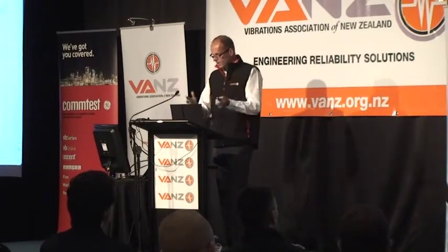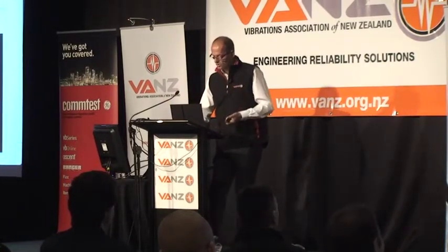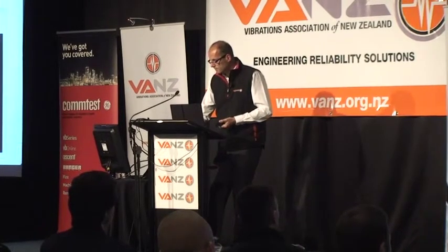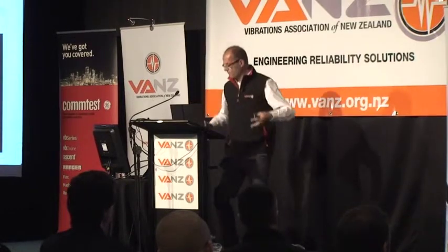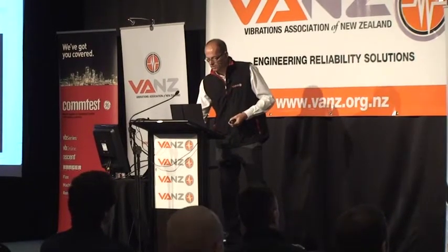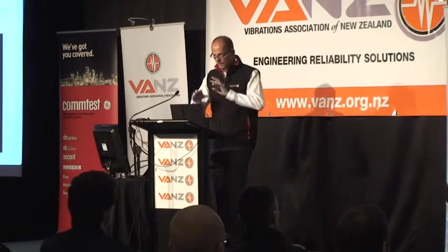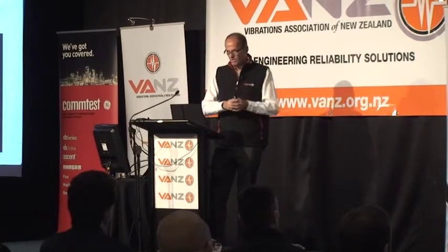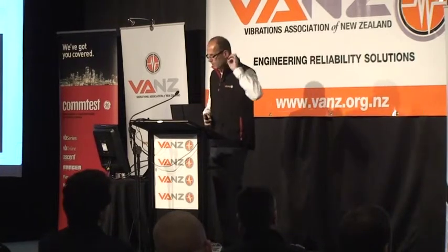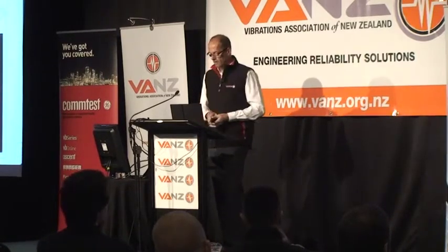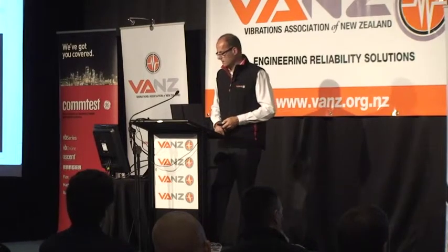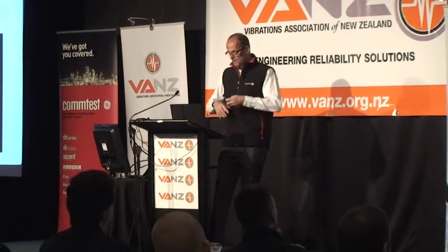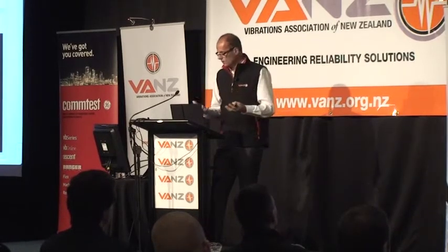So the machine makes all these sounds, and all we've got to do is use our vibration analyzer to say, let's listen to it here, because we can sense the vertical vibration, and we can listen to it over here, and as long as we're collecting the right information, then we can tell. We separate all those sounds into what's happening with the rotor bars, the bearings, and everything else. And like I say, I'll elaborate on that in just a moment. So vibration is great for rotating machinery, but there's much more we can learn with other technologies.